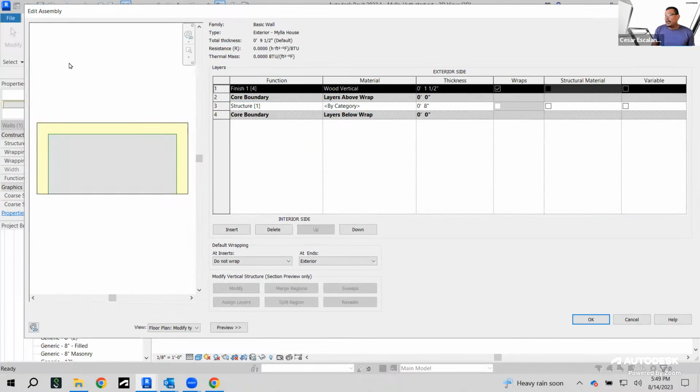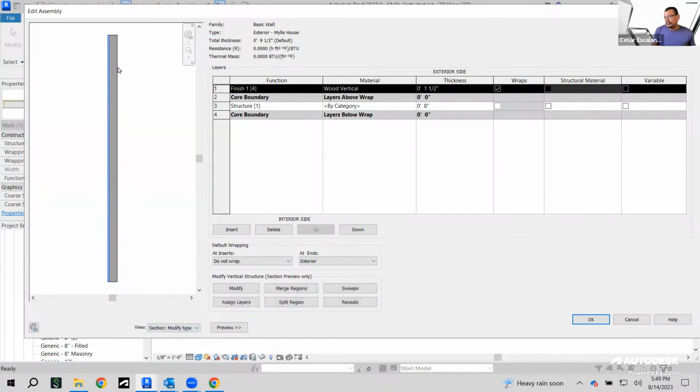The preview panel is a geometrical display of the partitioning plan, but you can also display it in section. In the lower right side of this panel, you can flip between a floor plan representation or a section representation.